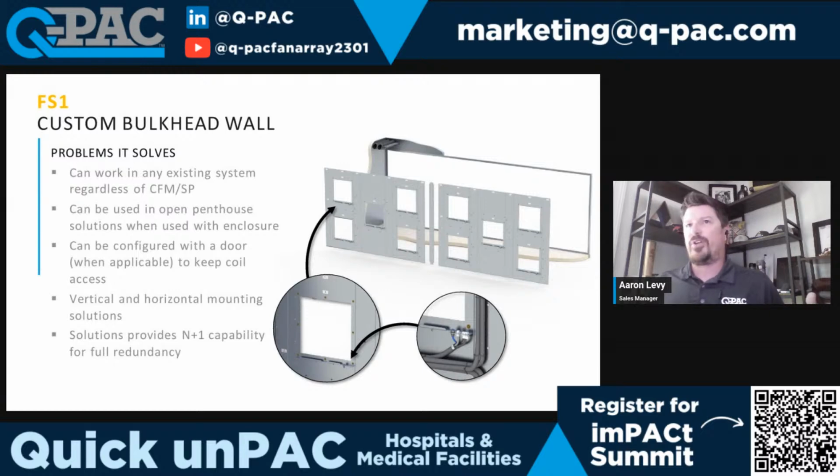We can also configure them, if space is provided, to add a door for access to the coil side. In a lot of cases when you're opening up some of these air handlers, the double width, double inlet blower system in general has walking access to the coil side for doing any cleaning or maintenance on the drain pans and things like that. By putting in one of these bulkhead walls, you do sometimes lose some of that access. If there's enough space and we can move the fans around inside the array, we can even add an access door, which restores the ability to get to that coil.